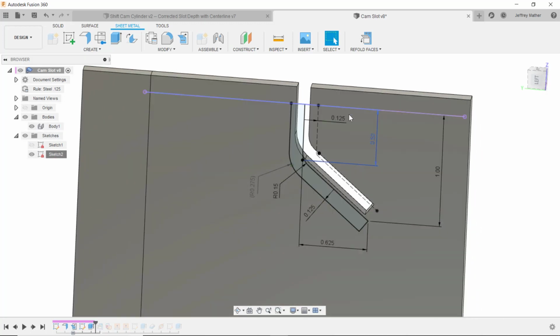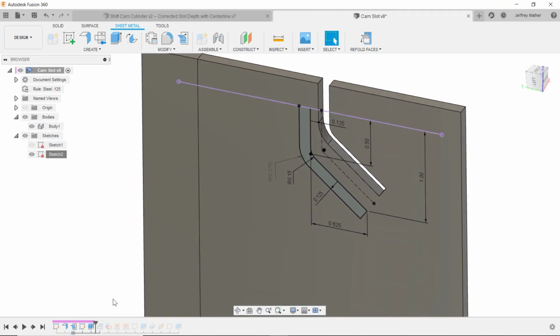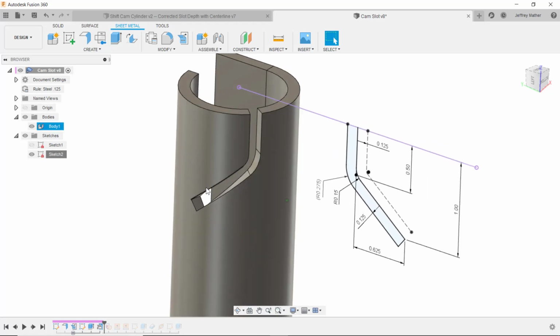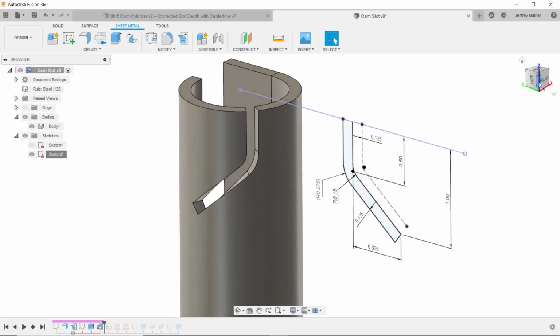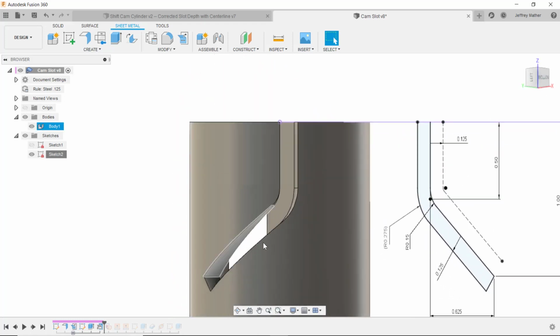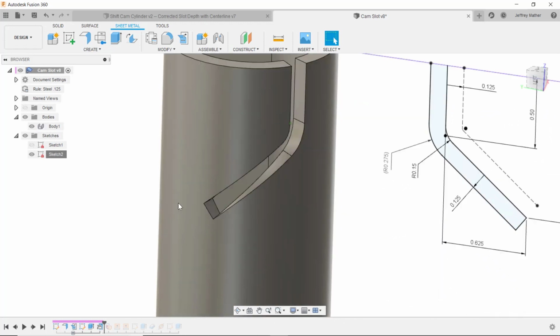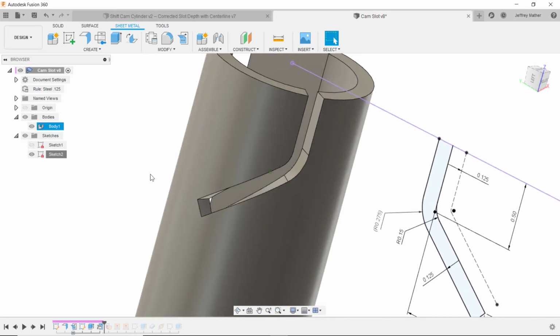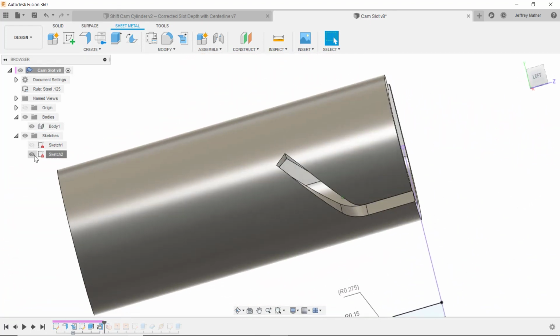And then I extrude cut that through this sheet metal part. I then refold the part back up again. Now this isn't as simple as you might think. Well, I'll just extrude cut through here, and that wouldn't give us this shape here. It's different. You can't just do a sweep either, a sweep of a rectangle, and I'll demonstrate why in a couple of minutes. Let's turn off that.